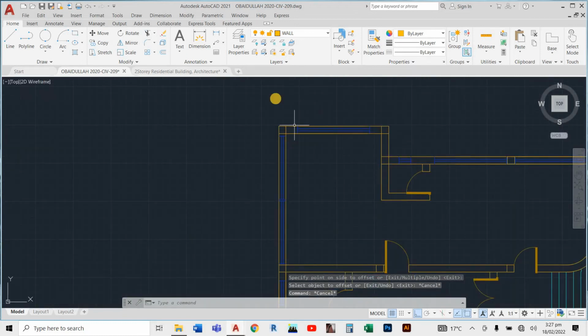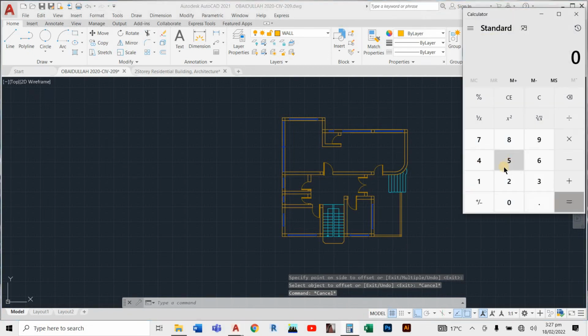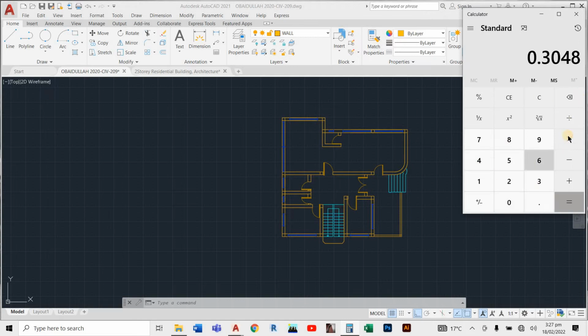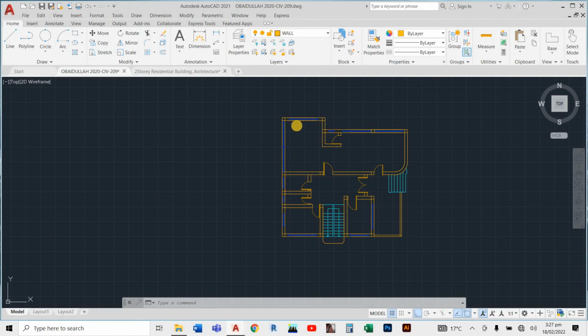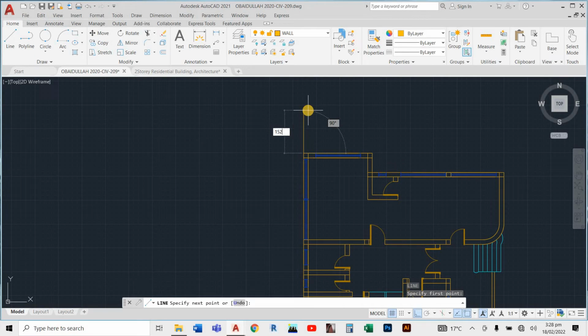and in here also we can define a boundary of 5 feet and 10 feet. How can we define this boundary? You have to change 5 feet into millimeters. So you know that 1 foot is 0.3048 meter, and 1 meter is 3.28 feet, and 1 meter is 1000 millimeters. So we have to take 0.3048 multiplied by 5 because we have 5 feet, and multiplied by 1000 because 1 meter is 1000 millimeters. It becomes 1524. Come 1524 and up to in here.